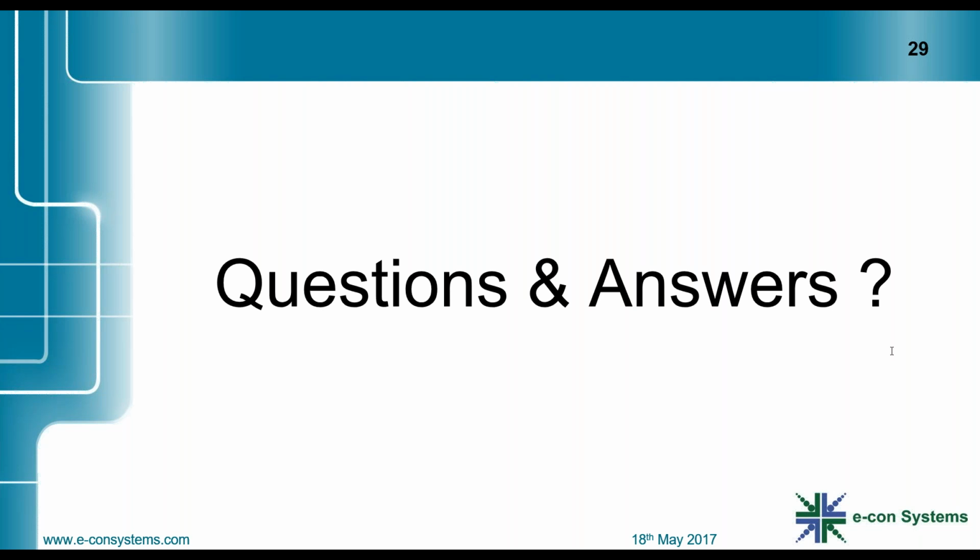Another question that we have received is, are the USB cameras compatible with the Jetson TX1 or TX2? And yes, sure, you can use the USB cameras that we provide with the Jetson TX1 and TX2. Not all the cameras will be fully compatible with the TX1 or TX2 because of the USB 3 limitation which is present on the TX1 or TX2. This is actually a host controller side limitation.